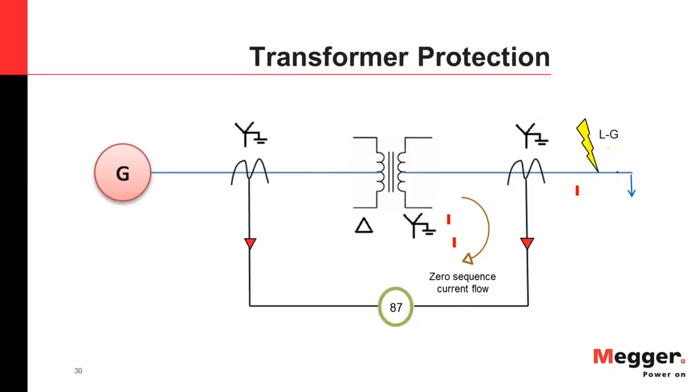But in the function that I showed, where you have both 51P and 51N elements on the same trip contact, then yeah, it might be a problem. Then you can go into the relay and disable the other element in order to test the element, but not many utilities would recommend that, because they don't want any change in the settings of the relay by a testing engineer.